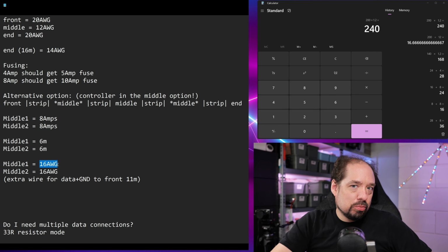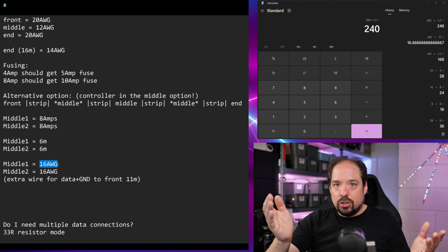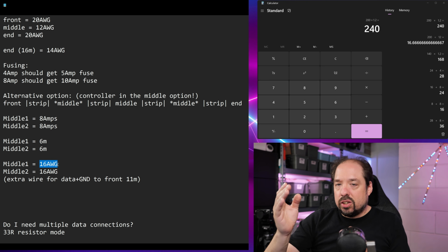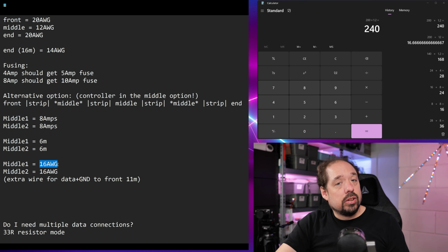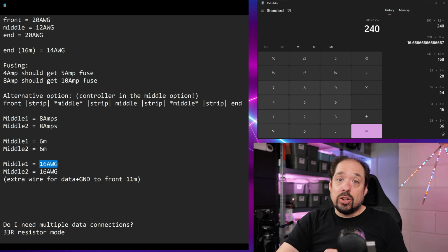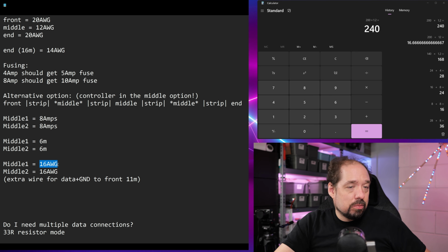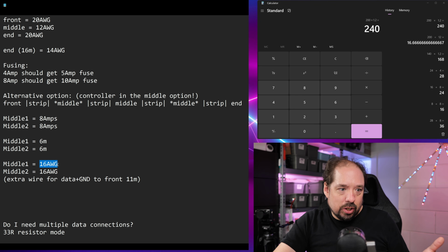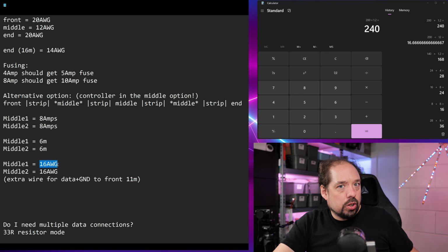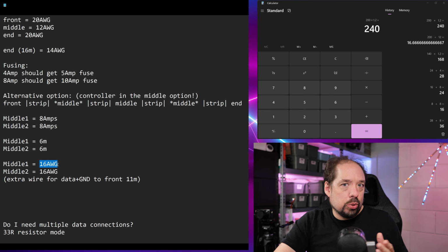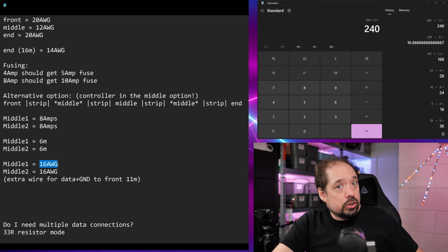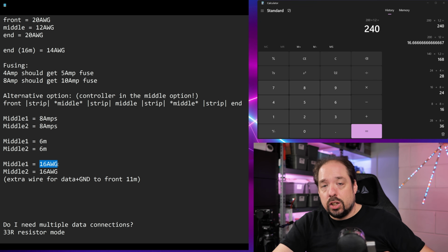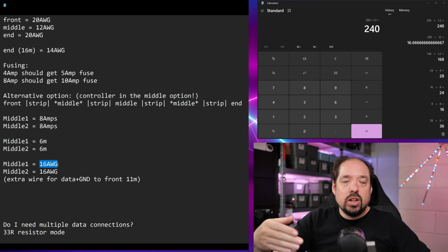So even though it's kind of the same scenario, we have single addressable LEDs. The only thing we changed is going to 12 volt. This already makes our life a lot easier. So if you're doing large scale projects, or projects in general, I'd say up to 10 meters, 5 volt LED strip, that can work. If you want to do 20 meters, go to buck converters or something like that, or go to a 12 volt strip like WS2815 or WS2811.